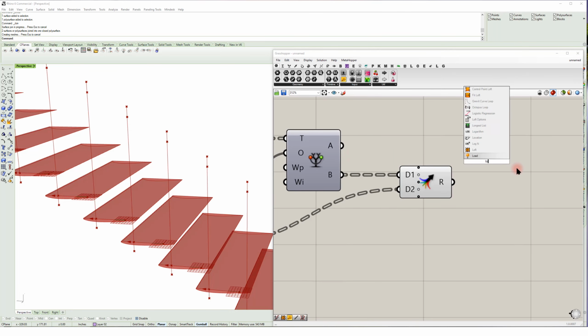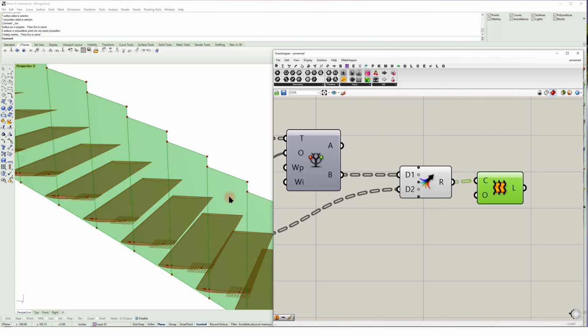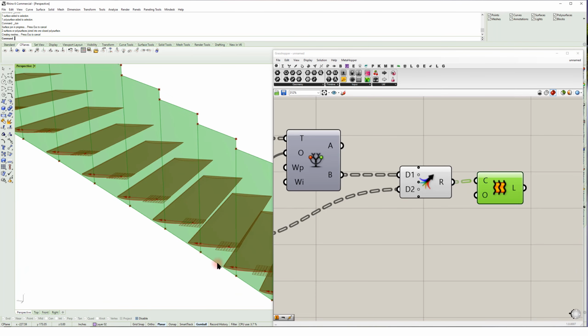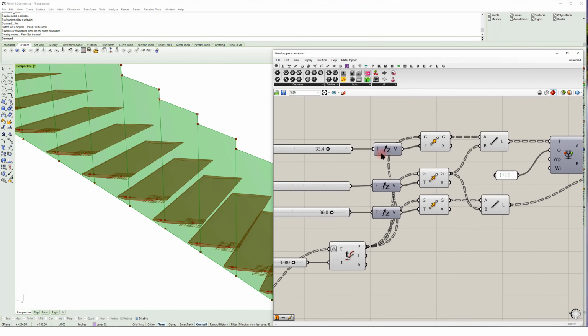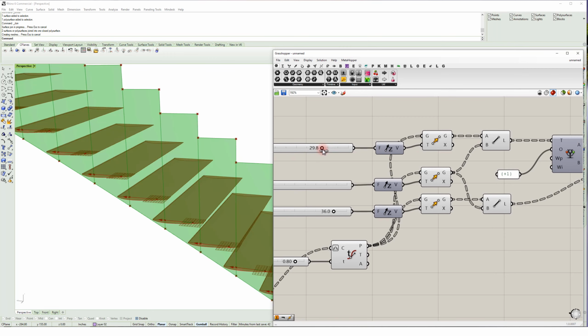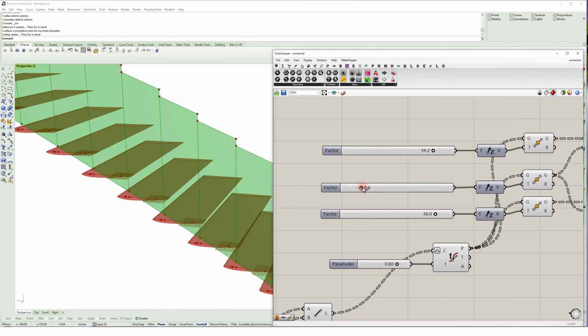So now if I loft, typing in loft, it's going to create a seamless sweep down here, and then it's got that flexible height up here, so you can see that shifting. And this, since they're using the same point, is going to be always tied together.